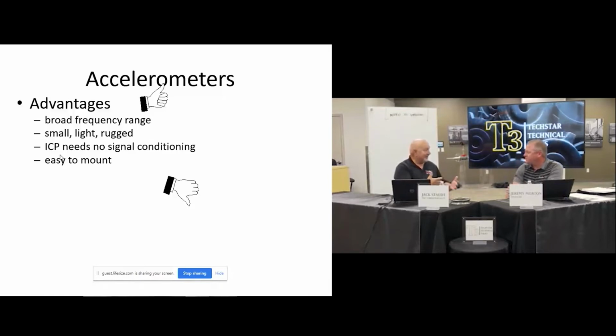Now, if you jar it, you get what we call the ski slope on the data. Also, if you're trending the data, you're going to have some type of wild anomaly in your trend data too. Is that typically the magnet on the bottom of the accelerometer? The guy hits record data and puts it on the bearing, and it impacts it, so you've got to wait for that to settle out. That's on the ones that are powered up when you turn the analyzer on, because it's already powered. Also, what you'll see is what I call a power jar.